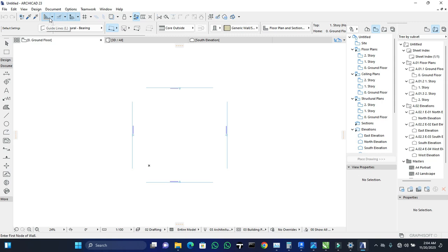So there's the guide line, these ones are to help you measure on your interface. There's the snap guide and points, the show and hide tracker, and the grid snap. In some ArchiCAD versions there used to be grids on the screen, and if you want to snap your drawing to those grids, you can just use the grid snap.